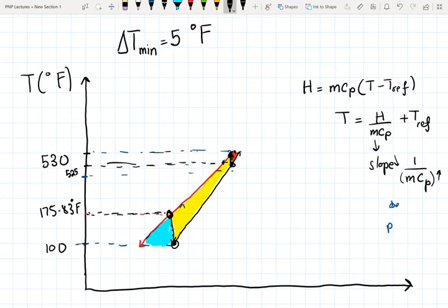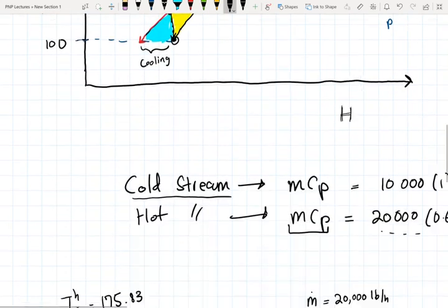But for the cooling region and the heating region, you're still going to need a heater and a cooler that either uses steam for heating or a hot oil, depending on the temperatures you're operating at. And those heaters and coolers will also need to be sized.